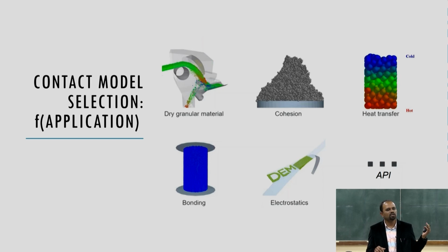So, DEM alone cannot do all the job, you need some CFD part also, since this is the fluid which is flowing in a continuous manner and we need a coupling of them. Then bonding models, bonded particle models are there, to create a bond between the internal particles. Then if you are interested in the electrostatic part, that is also there, so you can do that.